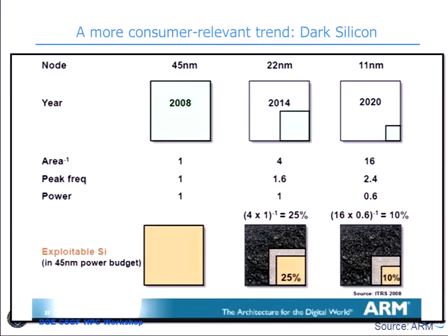If you look at, on the other hand, the power budget and how that's shrinking, basically what this is showing is that if you want to keep power constant or slightly less, due to some of the physics characteristics of silicon, you have to leave part of the chip powered off if you want to run that small part at the highest clock frequency that you can.